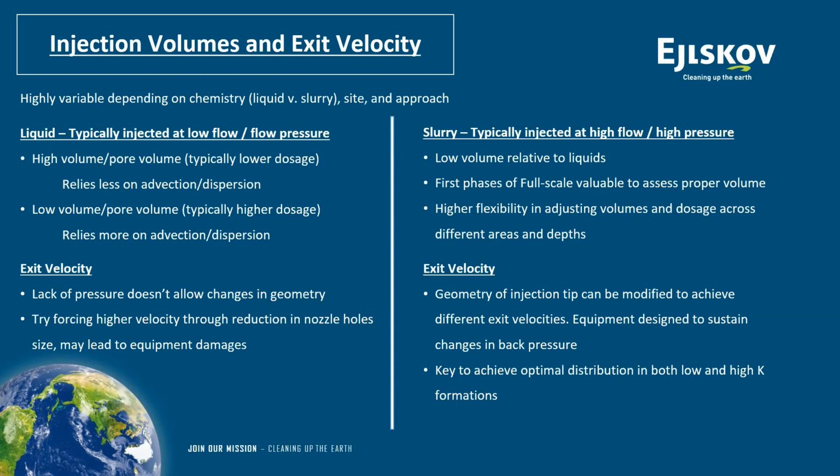So for example, if I'm working at a petroleum station, and you're working around, say, the UST cavity, your injection point spacing might be tighter, because we don't want to be pushing our fluid into that cavity. But the rest of the site, we might be able to have a larger spacing.